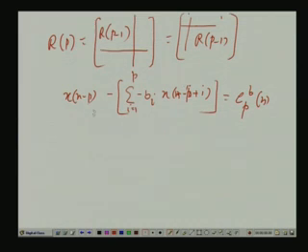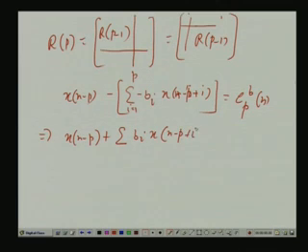So, what you get actually, minus minus become plus. So, you get, obviously, this is orthogonal to what? Orthogonal to the space spanned by those p future elements. Earlier it was p past elements, now p future elements. So, E p b n is orthogonal to x n, x n minus 1, x n minus 2 up to x n minus p plus 1. So, those p future values, if you go p steps in future from the sample x n minus p, those p future value samples are orthogonal to E p b n.